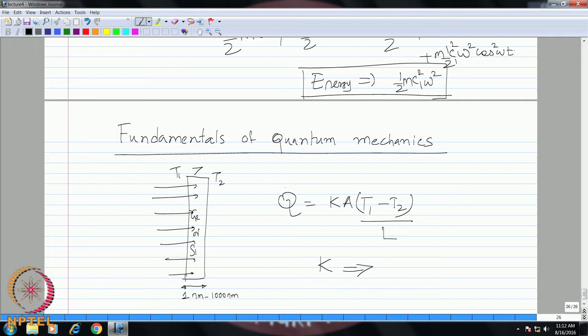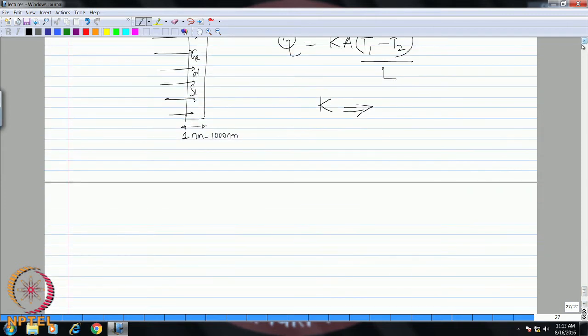That is a classical measurement, but surprisingly, when you use other methods, there are several other methods apart from the classical method, where you do not measure temperature directly, but you actually measure some kind of a pseudo temperature. One of the most commonly used methods is called the 3 omega technique. You pass some kind of a voltage at a frequency omega, AC current, and then you extract the third harmonic or 3 times omega component of this voltage, and if you plug it into a transient heat conduction equation, we can show that this third harmonic is directly a function of your temperature rise across this film, which is a function of the thermal conductivity. So, you can measure this indirectly.